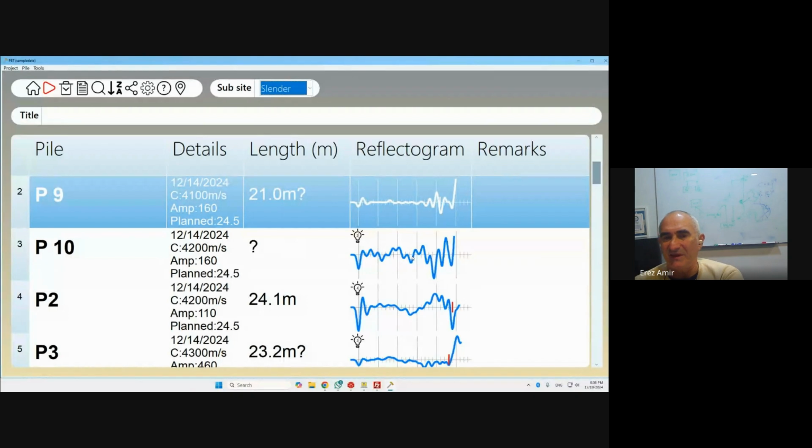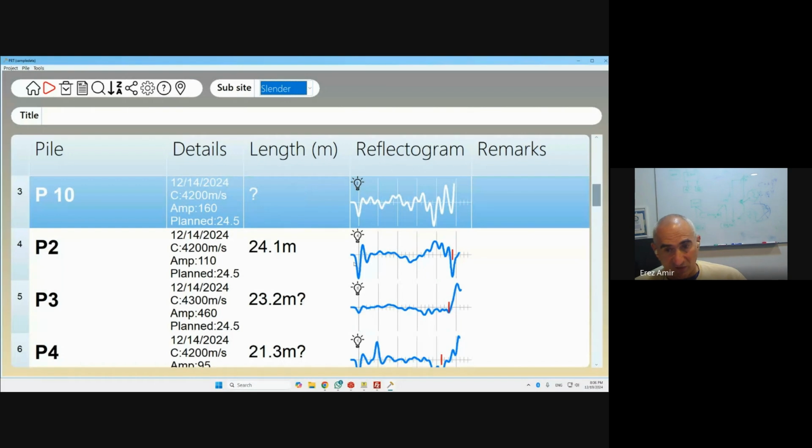So that's 50-something diameters. The SPT profile shows a varying SPT starting from 10 to 50. So that's a very stiff soil at the bottom, and 50 diameters with very high SPT values means that you're not going to get much.